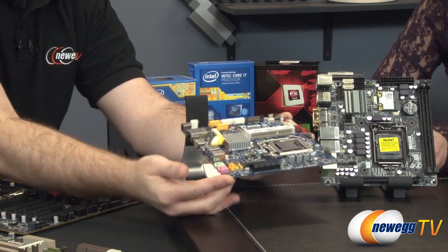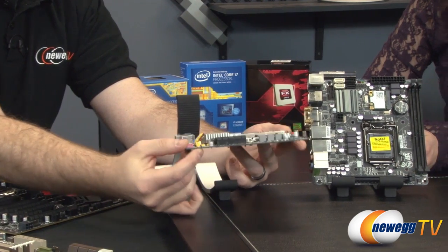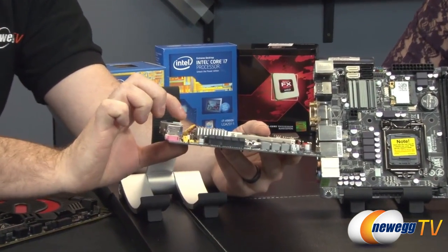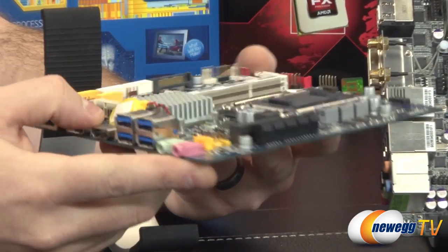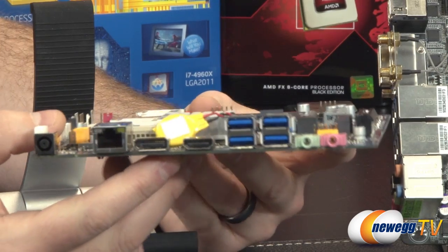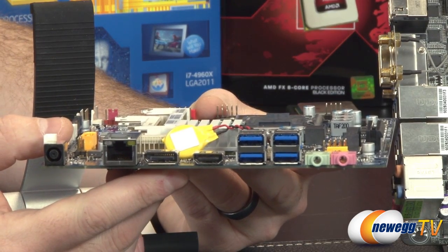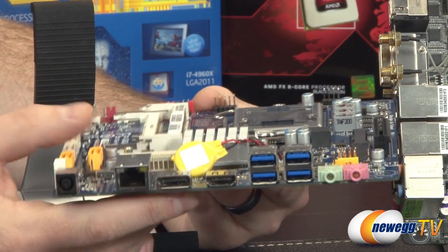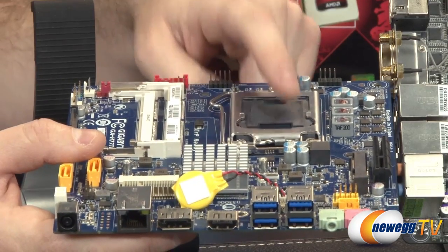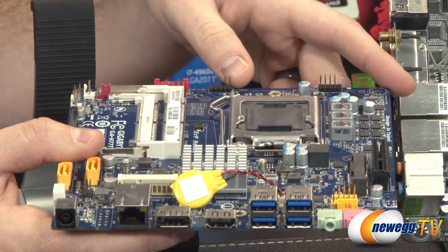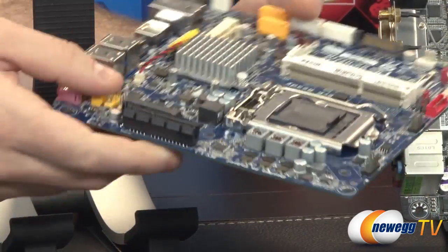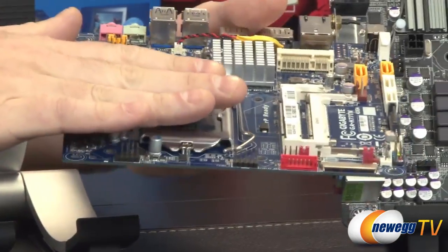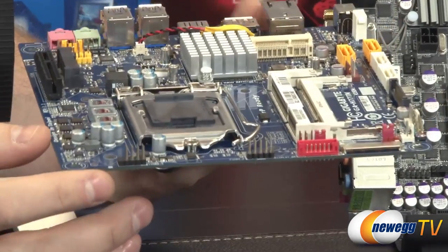But this is a thin mini ITX motherboard, which means it adheres to a standard for vertical height as well as the layout of the board itself. So you'll notice thin mini ITX is very thin. The I/O there, for example, is half the height, and this form factor actually has a specific positioning for the CPU socket right here, and then the coolers that you'll see for this board are actually very flat, so they lay down kind of on top of the CPU like that and expand off to the side.